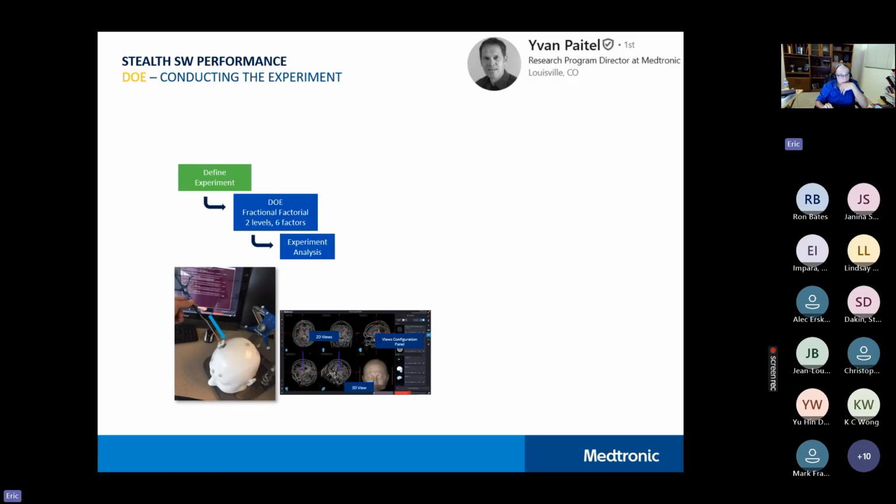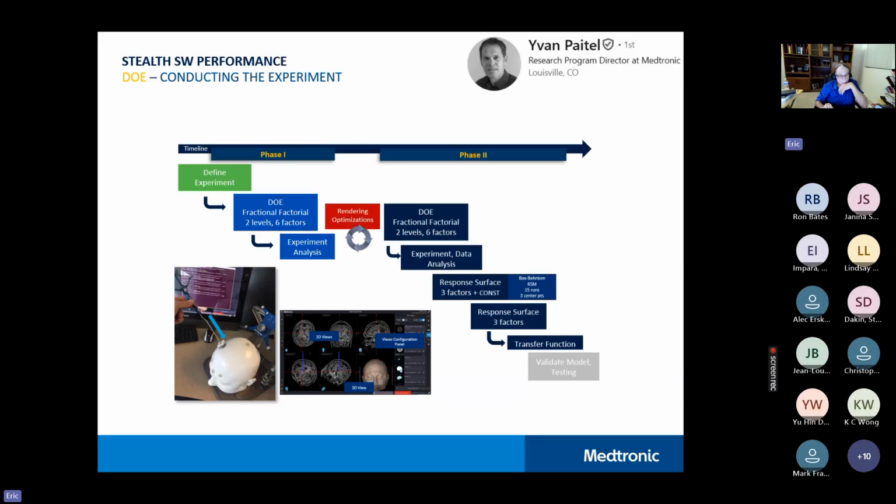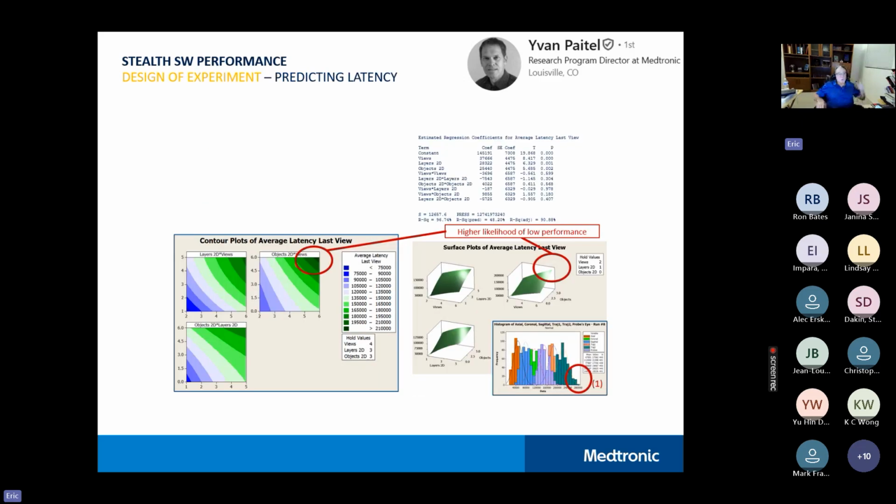So we did a first screening design of experiment with 6 factors, 2 levels each, and did a follow-up on that. Afterwards he came up with 3 factors that were very important to the response surface modeling, Box-Behnken design, to optimize the settings on that design. And this is showing you some of the results from that RSM,